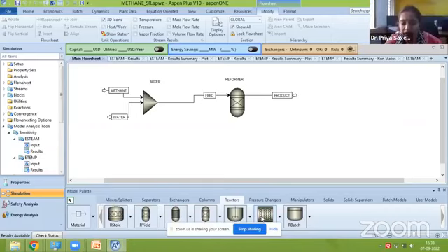Okay, and is any specific data required related to the catalyst? Everything is covered. For example, a catalyst alters the activation energy. So if we have the activation energy, as I have shown you, you can directly feed that in. A different catalyst is going to have different activation energies and pre-exponential factors. So ultimately, the effect of the catalyst is taken care of by those factors. Okay.